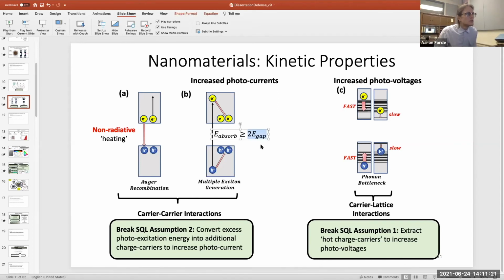So yes, you do still need a favorable band gap in the redder region, and there are established nanomaterials like, I can't think of which specific combination, but like cadmium selenide or cadmium sulfide. One of those has very low bulk band gaps, and when you quantum confine them, it reaches the optimal range.